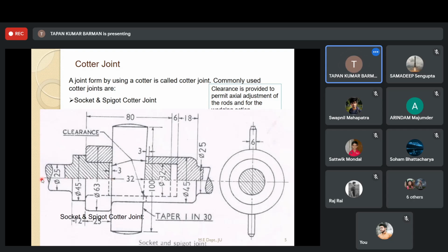Also here you should put the center line. Now there are two lines. So in between this zigzag line up to this, you should provide one firm line or continuous thick line. From here to here also, you should provide one continuous thick line. Beyond this point or beyond this point, this line should be your center line. Okay, sir, clear? Later on, one by one, I will try to explain.